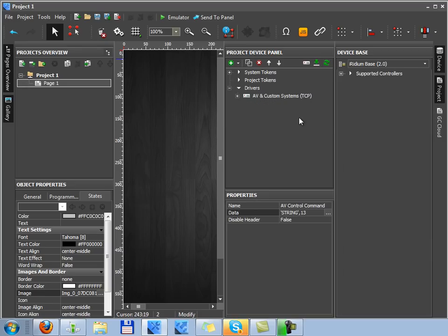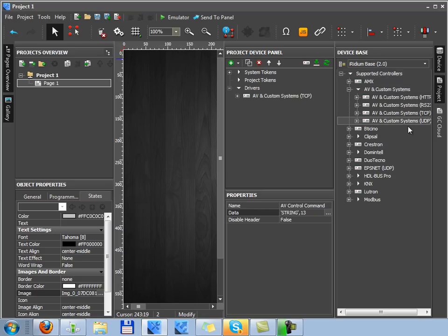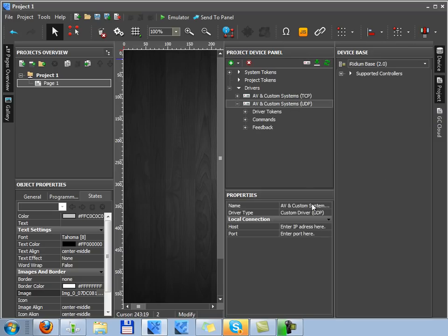Let's suppose that you have to send a data string via the UDP. The UDP driver must be also added to the project overview tree, and I have used the drag and drop method again. Host and port of connection must be set up, but in contrast with the TCP driver, we don't use a login and a password, which are necessary in order to open a protected session.